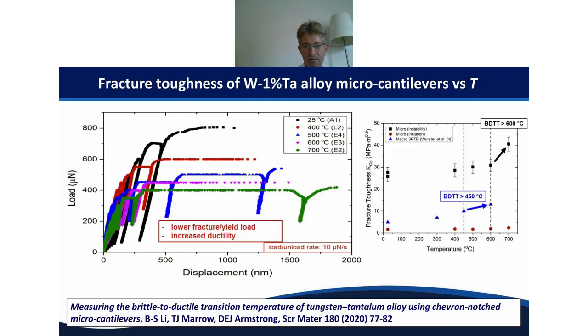So this is some more recent work by both Sharon Lee and Dave Armstrong at Oxford. And here they were interested in looking at the brittle-ductile transition of micro-scale cantilevers of tungsten tantalum alloy. Essentially, they've done load, partial unload, bend tests.